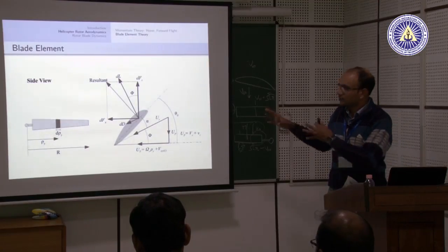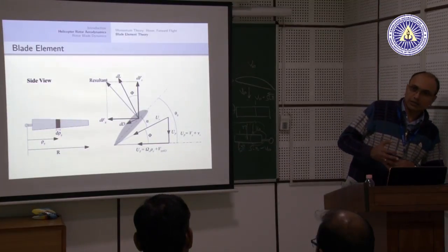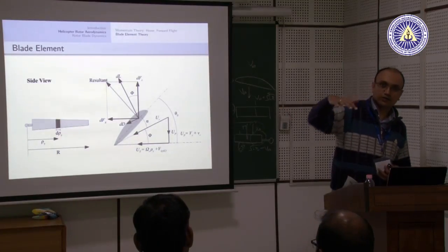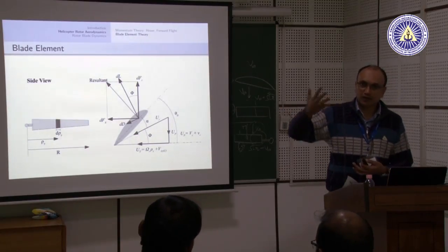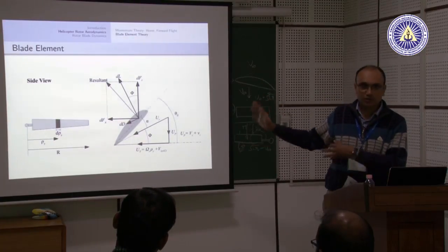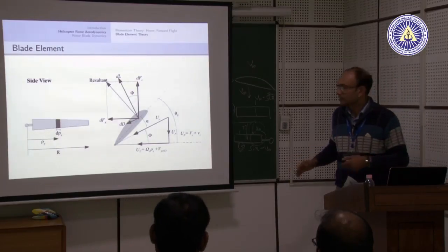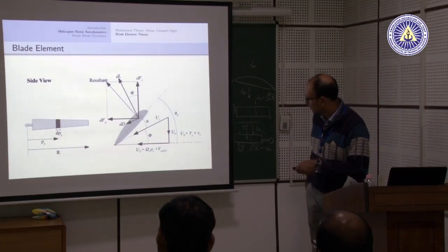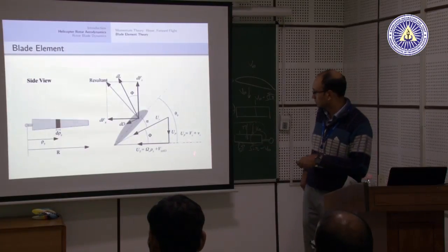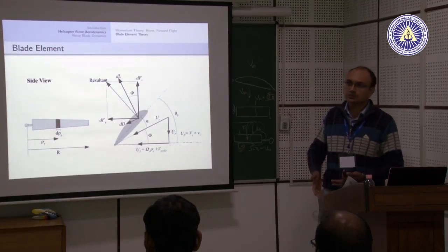So this same blade element theory, which we are looking at now, can be used to model a helicopter which is in hovering flight, in forward flight, or in maneuvering flight, any kind of general maneuvering flight, even flying upside down. So this same formulation, same theory, can be applied to model my rotor in any kind of flying condition by simply modifying this up, ut, and this third one ur. Depending on the flight condition, these velocities will get modified, but the overall fundamental principle remains the same.